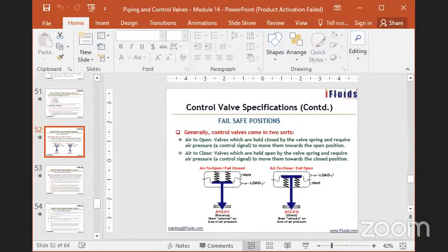So well fluid coming from the well reservoir is at a very high pressure, let us say 80 bar. I want to reduce the pressure to the operating level of the facility. Downstream of the choke valve it is, let us say, 30 bar. So I have to take a very high pressure drop of 50 bar, which means this kind of angle valves are used for very high pressure drop conditions. Angle valves are used for very specific applications. Next.